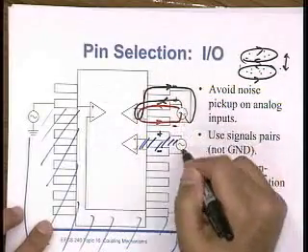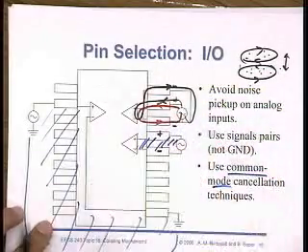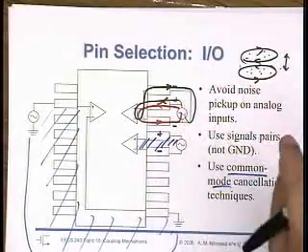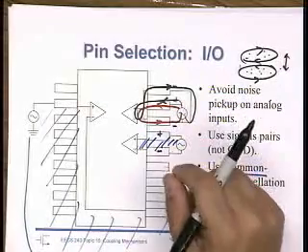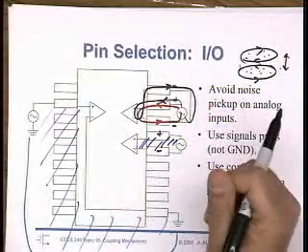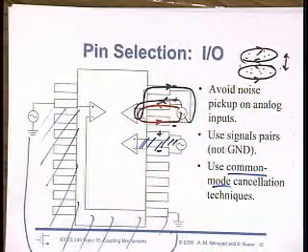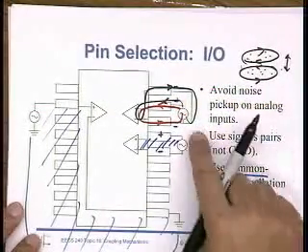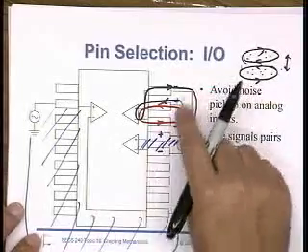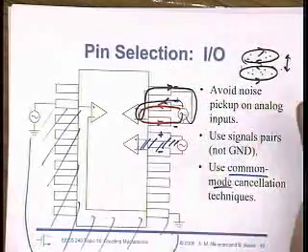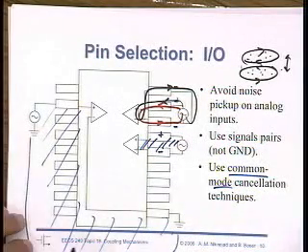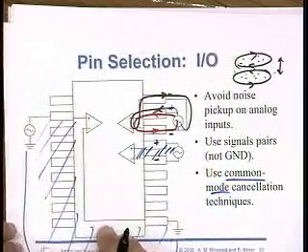And it's actually really neat. You go from a common mode input, so if you look at the noise on the input, it may go down from 10 millivolts down to a millivolt, in a power amplifier application. So it's a really cool way of getting rid of common mode noise. The other thing it does, of course, is now the input has two loops in parallel, right? And these two loops in parallel just have less inductance. So it has less inductance and it has less mutual pickup from other sources. Okay, questions?